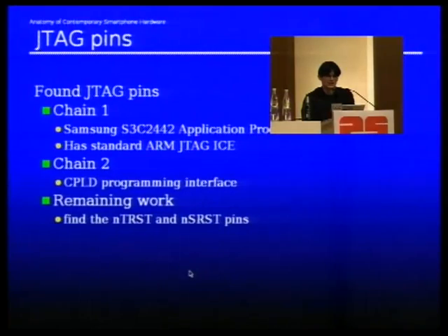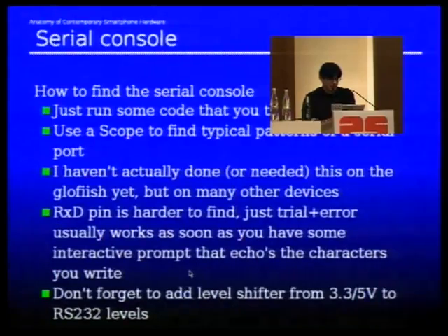And, well, interestingly, the device was able to find the JTAG chains both for the CPLD as well as for the application processor. And as soon as you have that, as I said, you can take full control over the system. You can do anything. Run your own code, single step through the existing code, do anything.